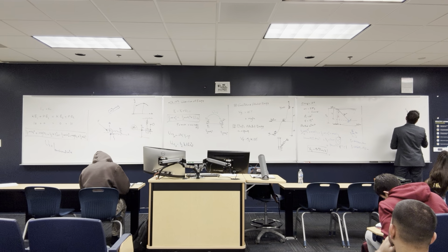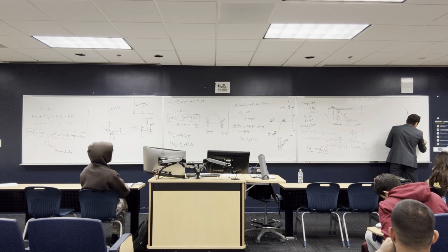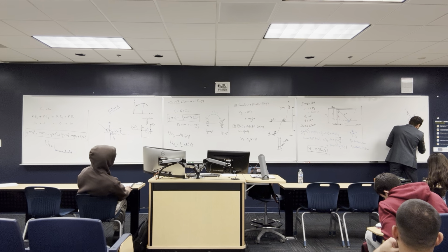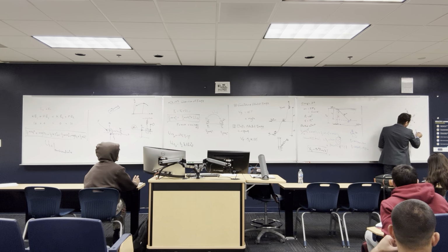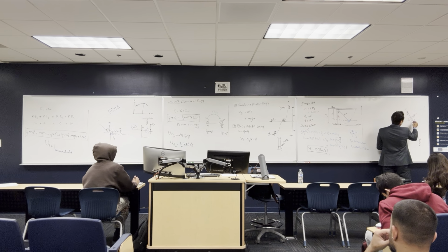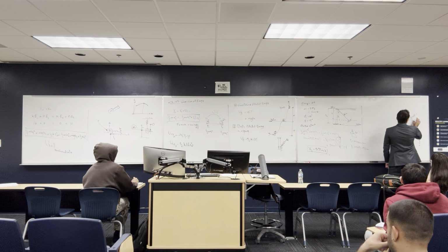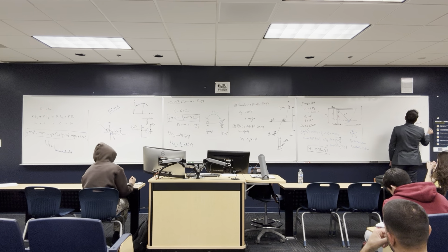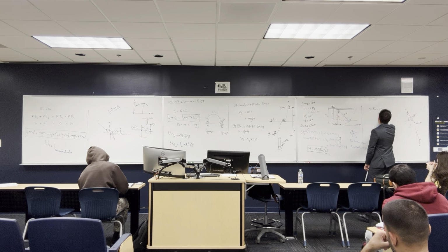Let's say this is here, and this is here, and my body's here, and this is the tangential direction, this is the W. If you take the extension here, this angle is going to be equal to this angle, because this line is parallel to this line. Same thing here. This angle is going to be equal to the same angle here. So this is 15 degrees. So I have here W sine 15 that way. So right now I can get the sum of the forces in the normal direction is equal to M AN.